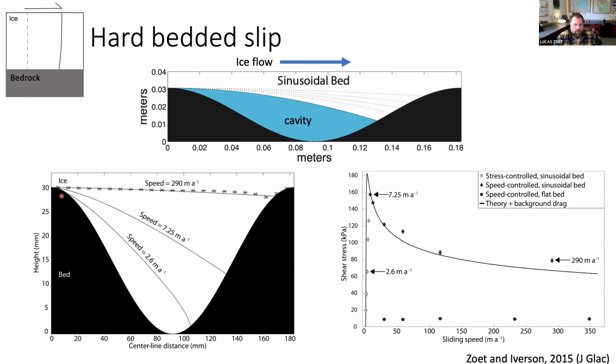And so this gives rise to different cavity sizes as the speed goes up, and that concentration of the stress in smaller and smaller areas as the cavity gets bigger produces an interesting drag response. So again, on the x-axis here is sliding speed, and the solid line is the resistance that we measured. And what you see is the resistance first goes up, hits some maximum, and then decays. And the reason it decays is because once the cavity gets big enough that it surpasses this inflection point, the resistance it can provide diminishes, right? And this is a so-called double-valued sliding law.